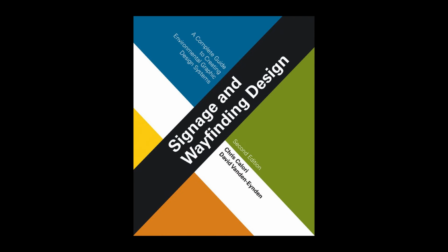Carbon steel. This metal is typically used for concealed medium weight to heavy weight sign structures, not for appearance. Other characteristics include high durability, heavy weight, and medium to high expense. Carbon steel also requires rust-inhibiting paints or coatings.